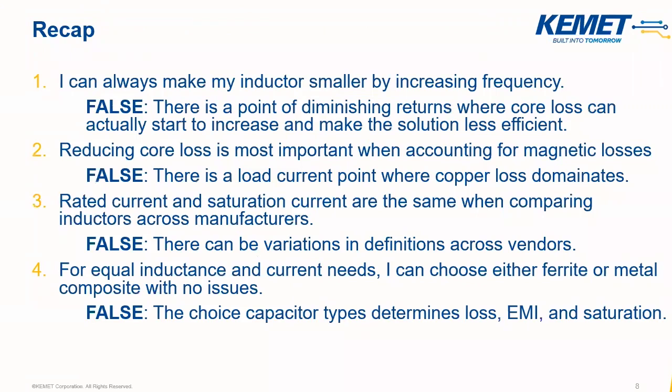Okay. Absolutely. So let's recap here a little bit. Let's go over these four myths that we just talked about. First off is this concept that I can always make my inductor smaller by increasing the switching frequency. And we've learned that there is a point of diminishing returns where that core loss can actually start to increase and make the solution less efficient overall.